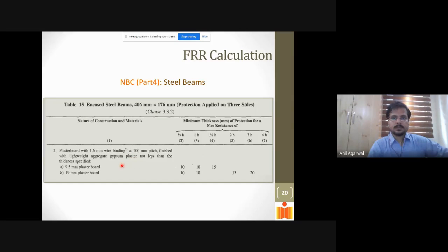Okay. So this table works for this section or bigger sections. Okay. Not for smaller sections. Likewise, there are tables available for a few sections in between. So then you can use the entire spectrum. Again, here it gives you requirements up to 3 hours of fire resistance. You cannot achieve 4 hours of fire resistance with these kind of methods.